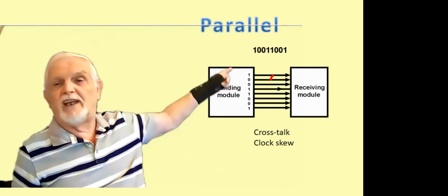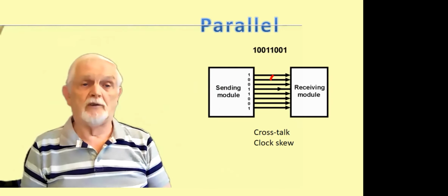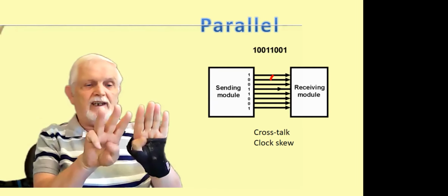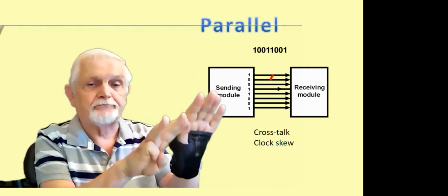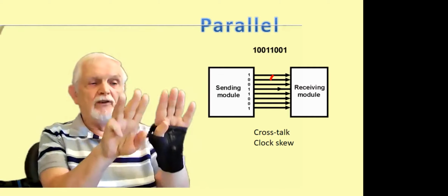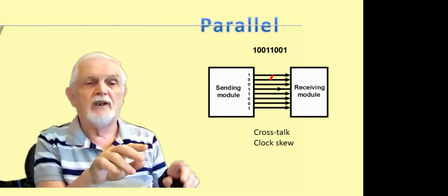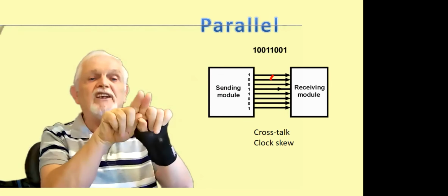You'll see the little bit of red I've marked here. Basically, we're talking about crosstalk. If you've got lots of wires, 8 of them coming down at the one time, then, as you saw earlier, they're very, very close together. And therefore, if one's meant to be at a 1 and the other's at a 0, there can be leakage between the 2.